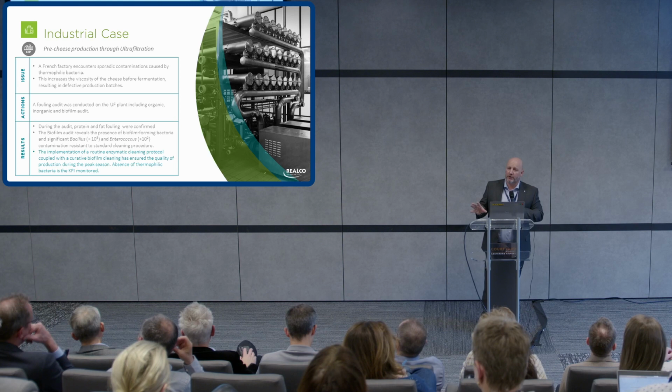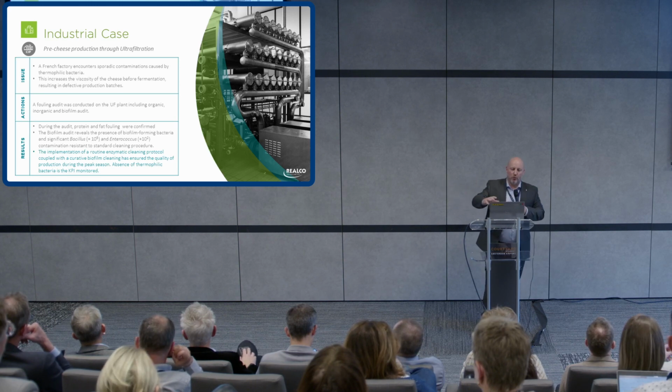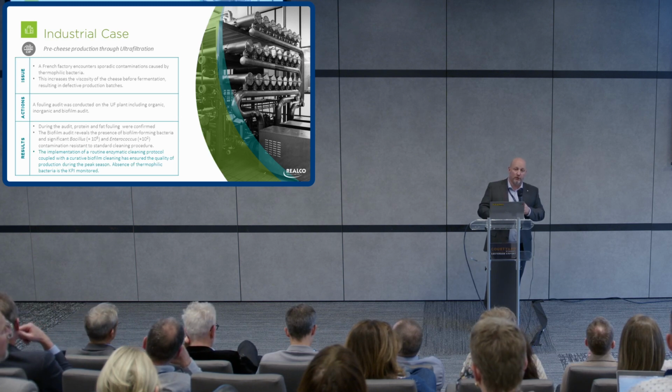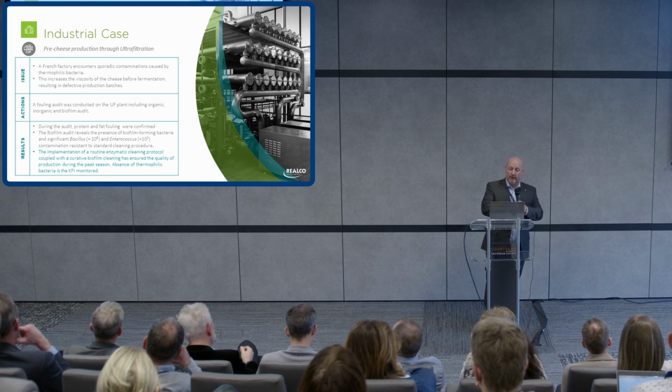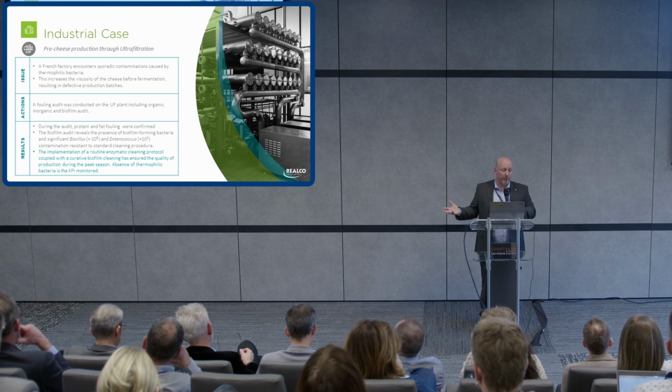And for the filtration application, we have an audit in 3 steps: organic fouling, inorganic fouling, and biofilm fouling. So we investigated, and we understood that proteins and fat were present in the equipment, so they had to reinforce the cleaning, but they also had to take care of the biofilm because biofilm was growing in the equipment.